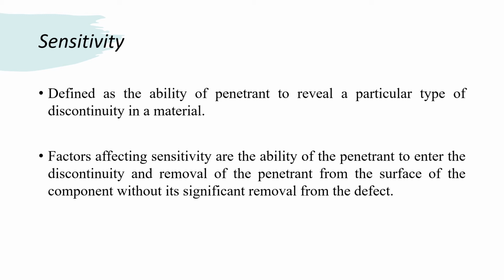That means the penetrant must have the ability to come out of the discontinuity with the aid of developer, and to form an indication which is readily visible and with good contrast with respect to the background.